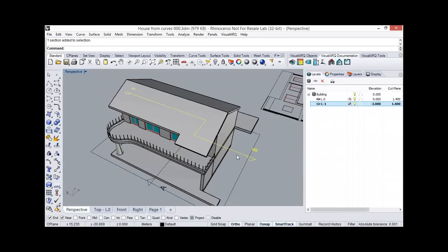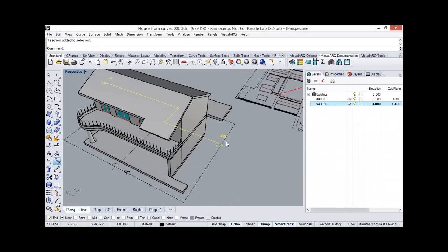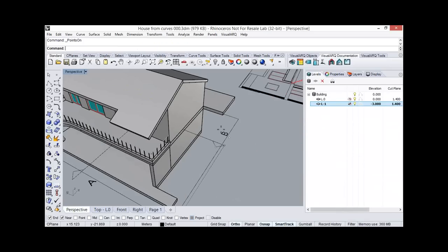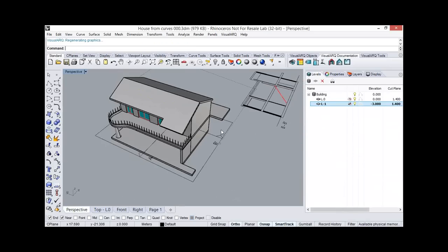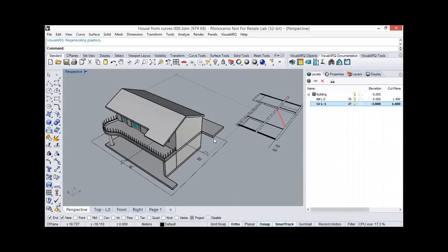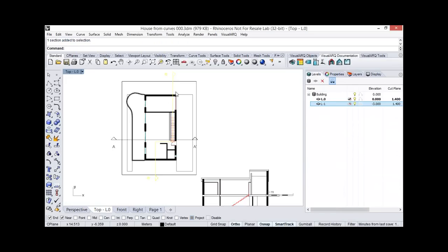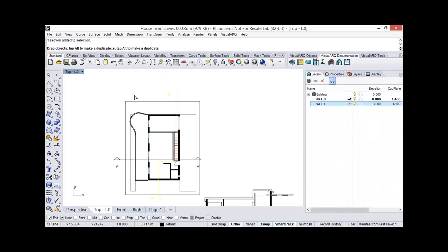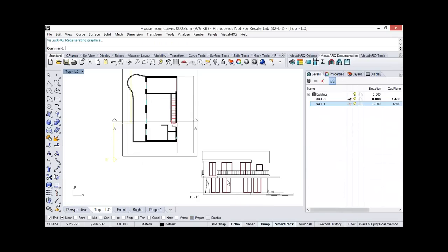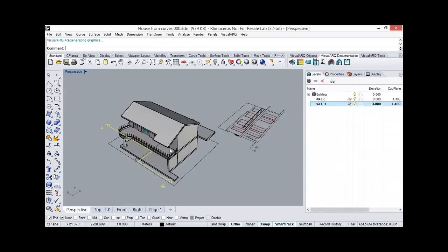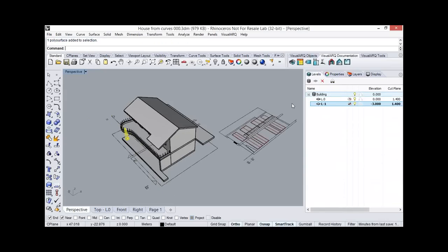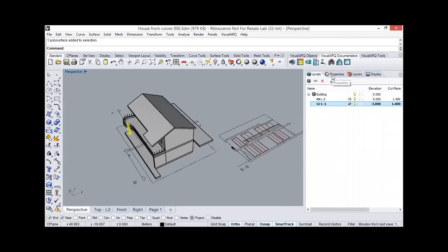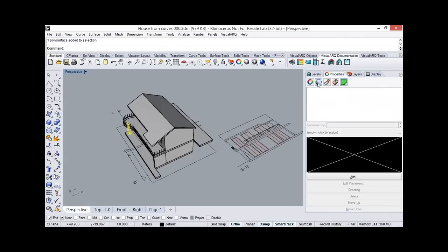And actually we can flip the direction of the section view from here. The drawing updates automatically, okay. And we can move that to any position, okay. And as you can see here, the section automatically updates according to the drawing. So we can now assign some attributes to this object, which is basically Rhino geometry, as I showed you before.